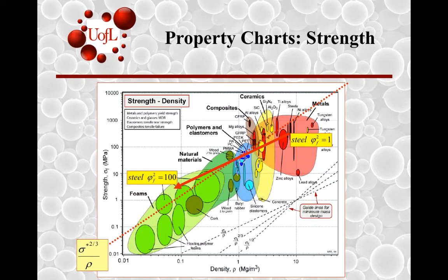So, do you remember? It would be sigma f divided by phi square. So instead of 7.8, it would be about 0.078, which will be roughly over here in density. And instead of about 120 megapascals in strength, you would come down to about 1 megapascal in strength.